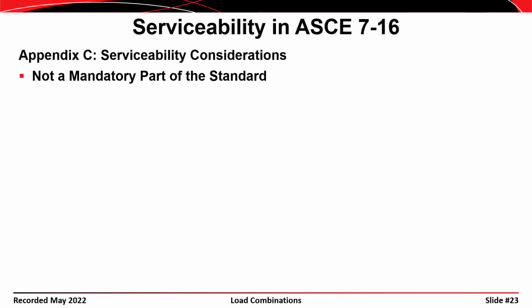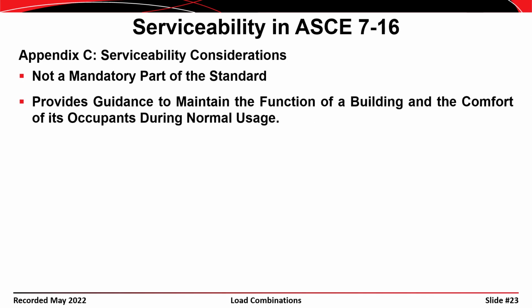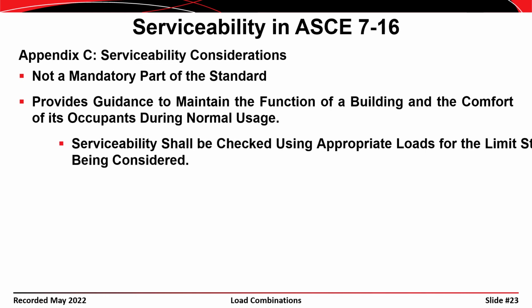If we look at ASCE 7, Appendix C of that standard includes serviceability considerations, but these are not a mandatory part of the standard. They do provide guidance for the maintenance of the function of the building and the comfort of the occupants during its normal use. It covers things like vibration, drift, and beam deflections, things of that nature.